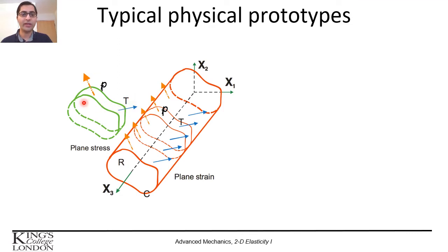So basically we can just cut a single plane out of the body and assume the only forces acting on that small element are acting on a plane with no traction or no forces perpendicular to that plane. That's the case of plane stress.